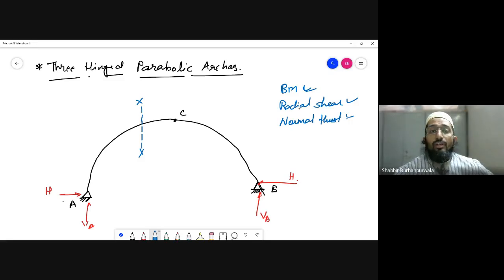First is what? It is the axial force diagram we make. Okay, so axial force which is acting on this section, which is compression or tension. Then the second type of force or stress that can act on the member is shear force, which acts perpendicular to the neutral axis. Okay. Then there is the third type of stress, which is acting in terms of bending.